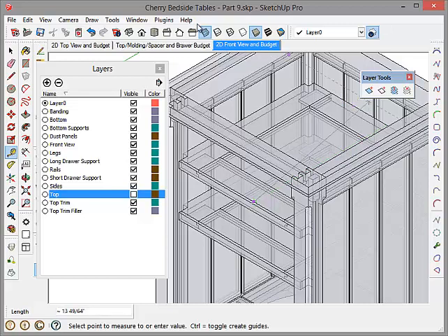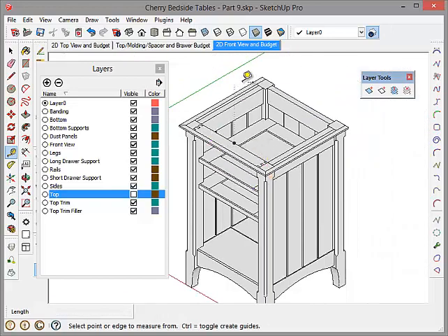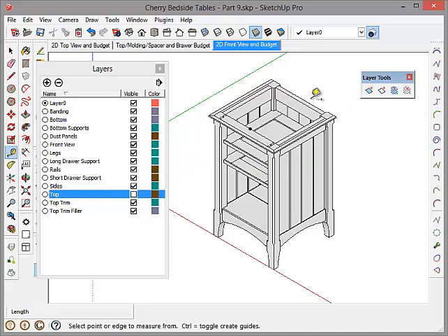Okay, now I can get rid of my x-ray and my tool. And now that I know the size of the box that I want to design for the drawers, I can do some calculations that leave a little margin for expansion and contraction. All right, offline I did a little calculating, and what I decided was that the box height is going to be 1/4 inch less than the box opening height. So the box opening height is 4 3/8. We'll make the box height 4 1/8.